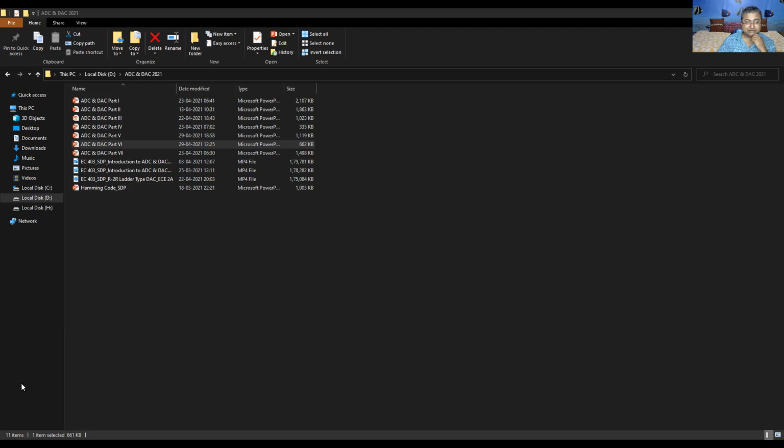Since the positive analog input voltage is connected to the inverting input of the integrator, the output V1 is a negative ramp. While the comparator output VC is positive, the clock is passed through the AND gate, and this results in counting up of the 4-bit decade counter.